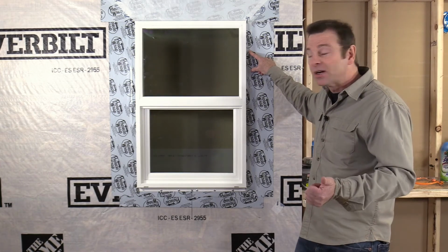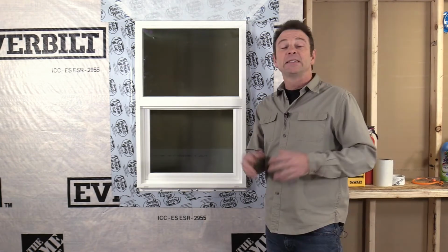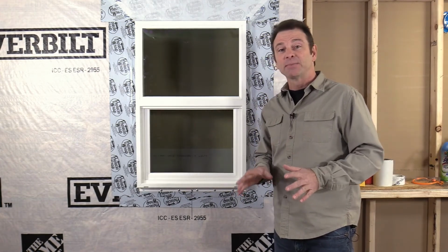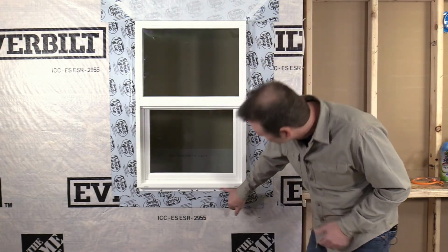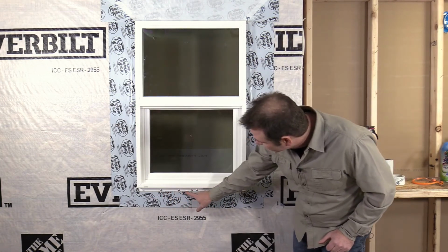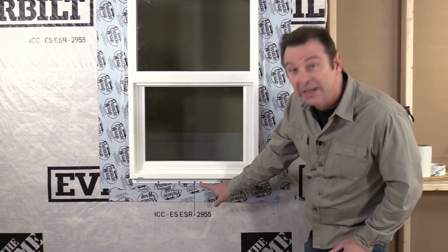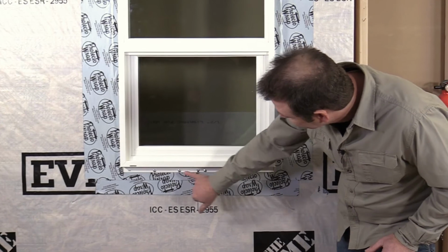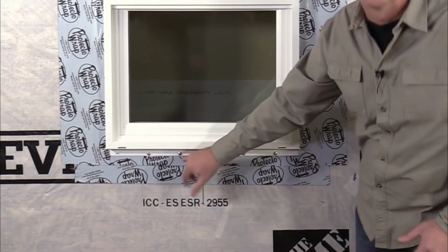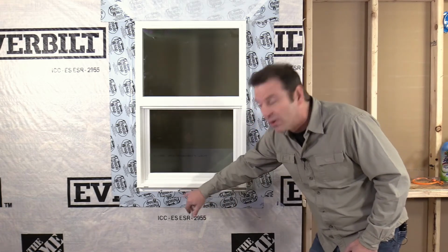The other spec that they call out is a spacing all along the perimeter. It's interesting because this manufacturer spelled out a specific spacing of 7 inches max for the perimeter fasteners. Well, my holes are set at 4 inches. So I couldn't skip any holes. That would put me at 8 inches, which is out of my spec. So we're putting in more fasteners, one every 4 inches.